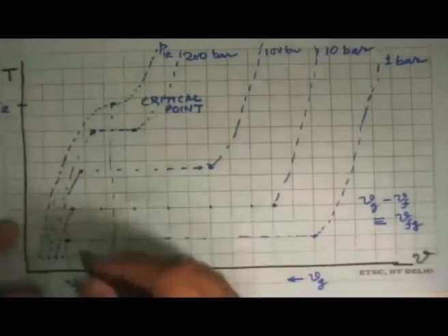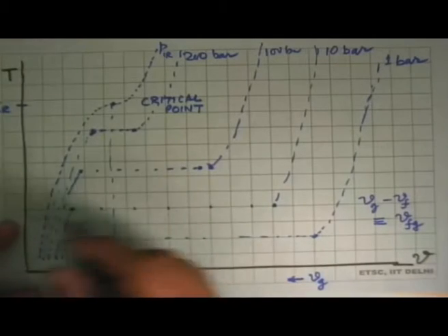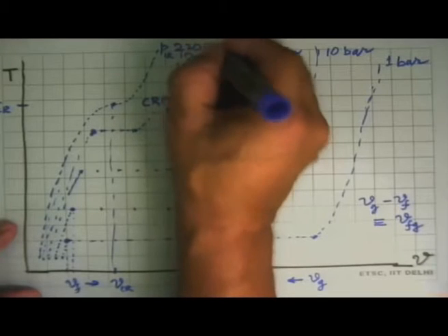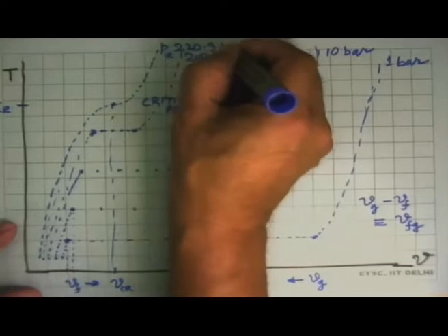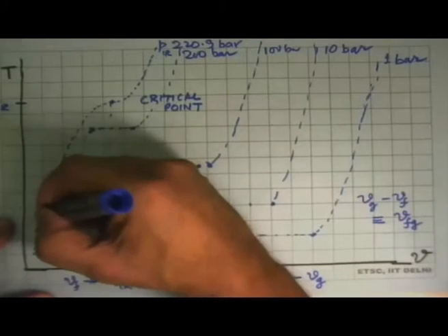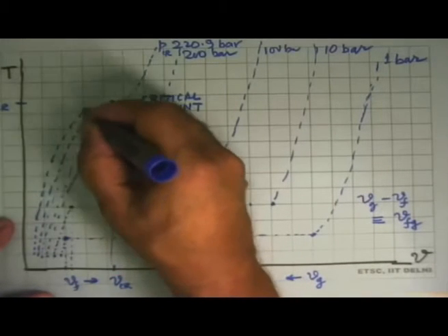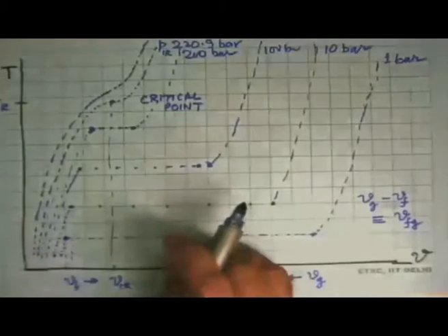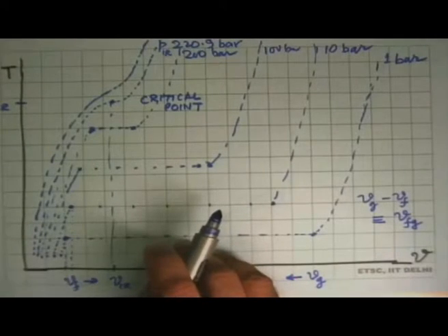And what it tells us is that if you do this isobaric heating at pressures, for water, this is about 220.9 or 220.6 bar, something like that. And at even higher pressures, at 300 bar, this line will go up and just continue like that. It will never come to a zero slope.